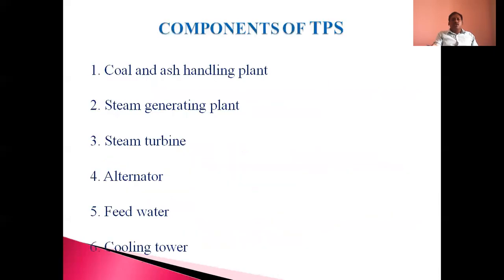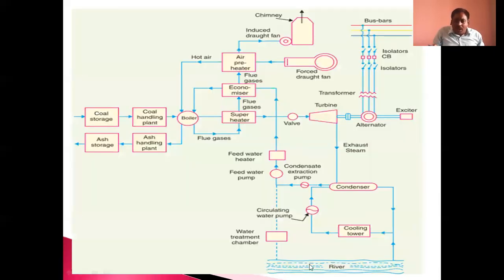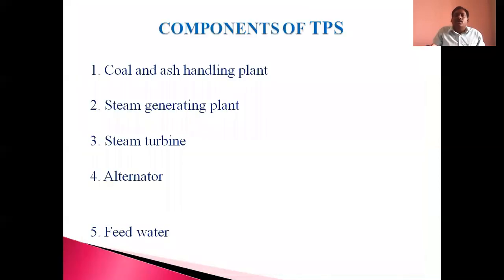So if you observe the layout of the thermal power station, the water that comes from the river or lakes is fed to the boiler in this line diagram. Through this economizer, the feed water is delivered to the boiler. In this journey, the economizer takes in the heat from the flue gases and that heat is delivered to the feed water. Then the water is heated, and the burden on the coal conversion is also reduced. That's why it also increases the thermal efficiency of the system. That's why the economizer is called a feed water heater.